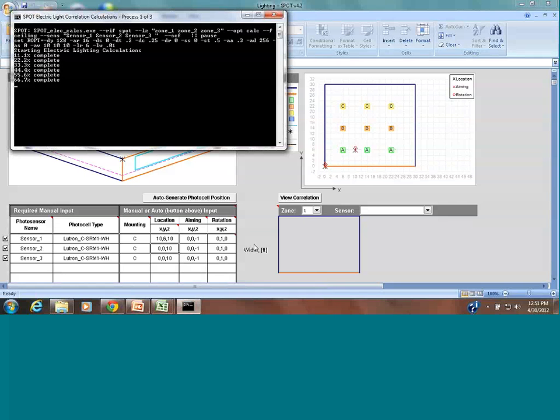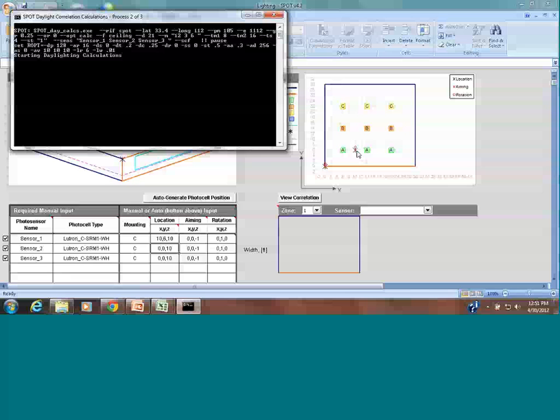Typically in our classrooms, at least in the last few jobs, we've had only one sensor located close to the window. So our window's on the south side, one sensor located close to the window, and the additional electrical light fixture arrays or zones will be controlled based on an algorithm. So, for instance, if this light fixture array sees enough light, so it says it can turn off 100% of all of these lights, then we can program an algorithm to turn the second zone or array B, this row, to maybe 60% down, and then the third row to be maybe 30% down, depending on the daylighting penetration design that you've come up with.